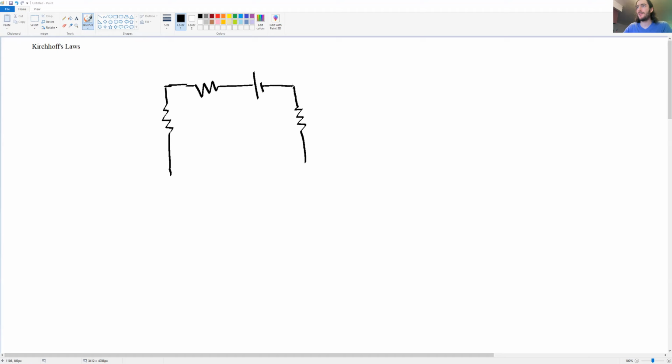We all know that batteries eventually die off, and that is modeled as the internal resistance of the battery increasing over time until it gets to the point where there just isn't enough juice left in the battery, in other words, enough chemical potential energy left in the battery to keep current flowing in the circuit.